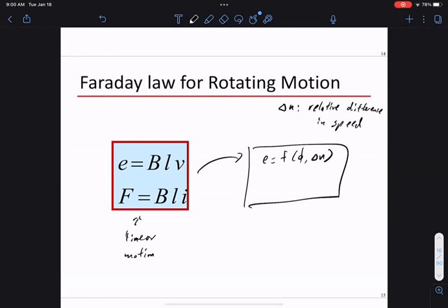Right, so if our external field is turning at n_s, at some synchronous frequency, and you turn at a different frequency, then you generate some voltage. And because you generate this voltage, again, this is a conductor, you feel current and torque. Okay, you generate some torque. So this is angular momentum or angular motion.